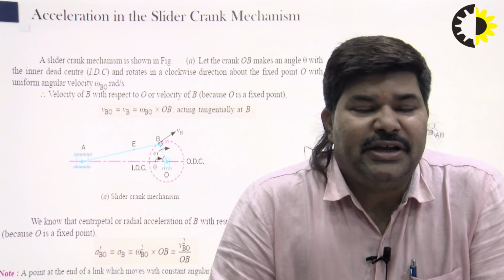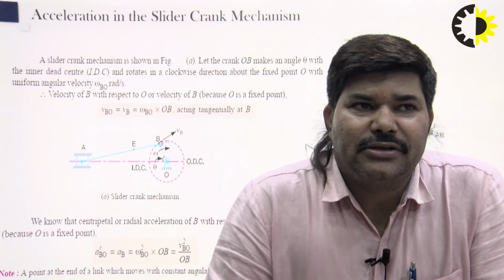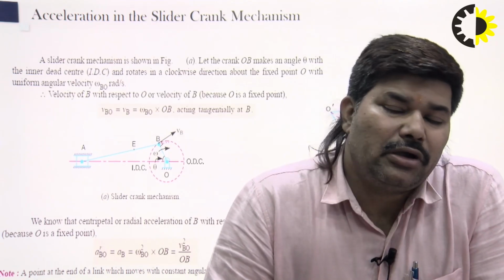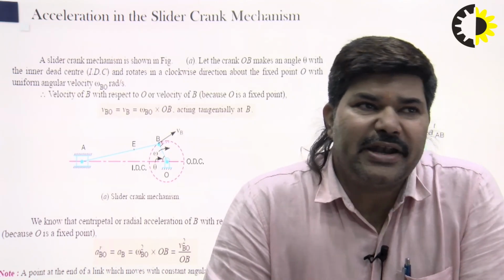So, you can see in this figure the crank OB makes an angle theta from the inner dead center and rotates in the clockwise direction about the fixed point O with a uniform angular velocity omega radian per second.